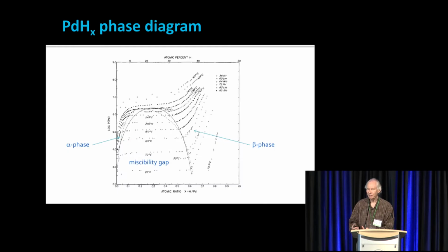So I want to begin by thinking about alpha phase models. If I look at the phase diagram, and this phase diagram would be the transient phase diagram. Mike Staker the other day talked a little bit about the equilibrium phase diagram. And in this presentation, I'm assuming that the atomic self-diffusion of palladium is sufficiently slow that we're not getting vacancies. So all of my palladium atoms are locked into an FCC-type lattice for this discussion.